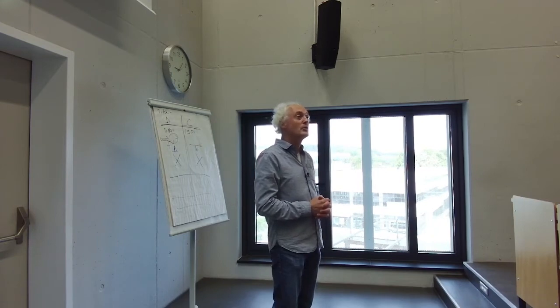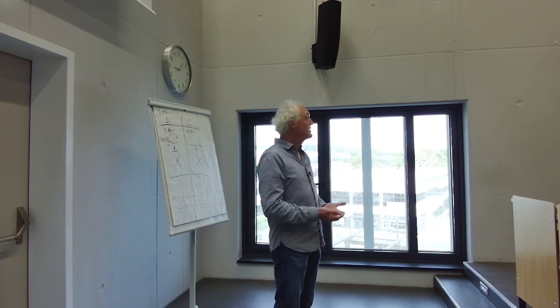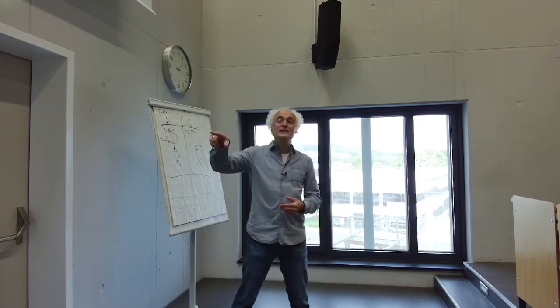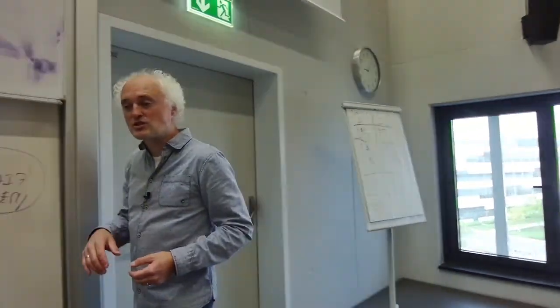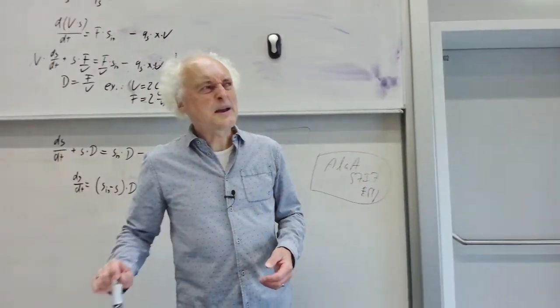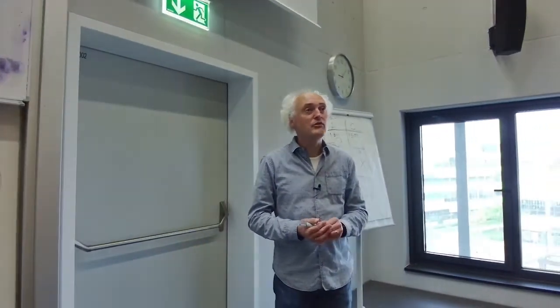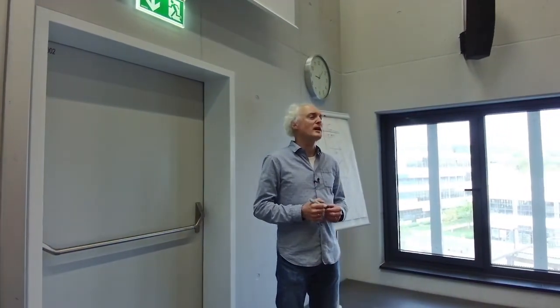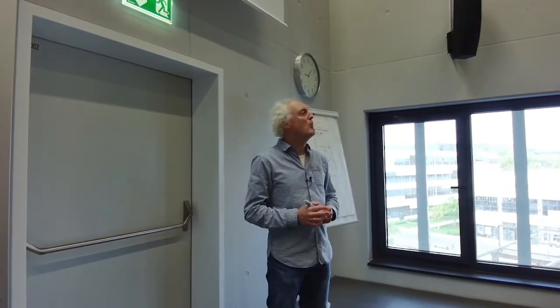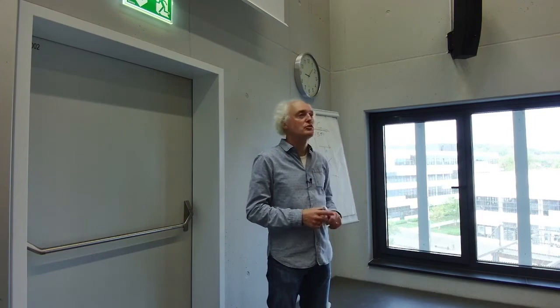And I want to know now, what is my optimal feed rate in this case? And this I can deduce now from this equation. If I make a couple of assumptions, I say, well, the substrate concentration in my culture itself will be quite small, and I assume it's almost constant in relation to the other things.